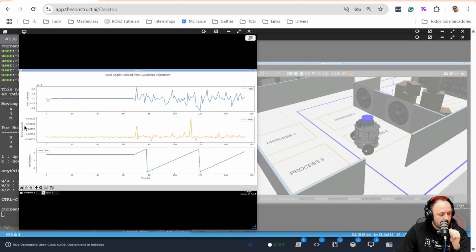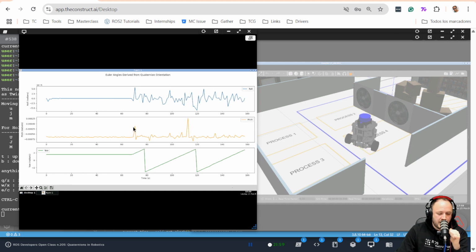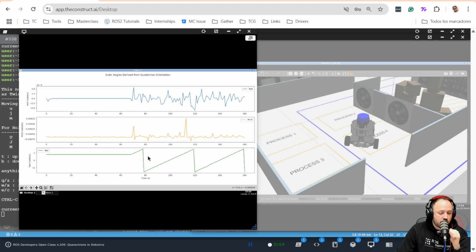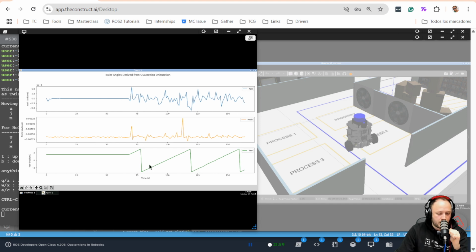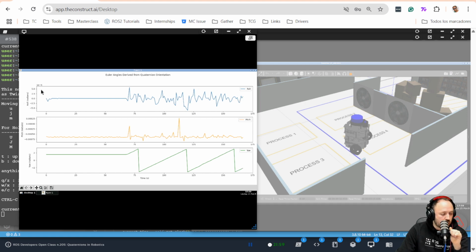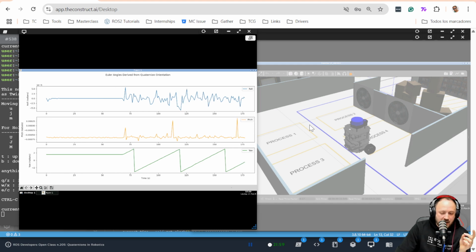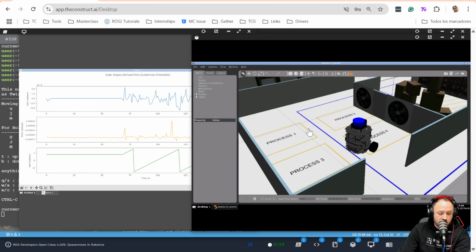Now, in a gimbal lock system, what we would see typically is it would happen when the pitch axis reaches 90 degrees. Typically, then we would see some strange behaviors like very big jumps or misreadings, etc., either in yaw or in roll. So this can be used to detect gimbal locks in more complex systems. Again, not here because this is not a gimbal lock.